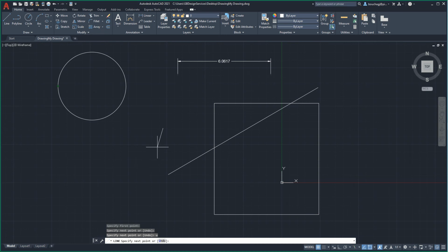The intersection Object Snap is represented by a green X and will be displayed where geometry intersects other segments of geometry on the same Z plane. The insertion point Object Snap is represented by a pair of offset green boxes and indicates the insertion location of objects such as blocks, text, and other attribute